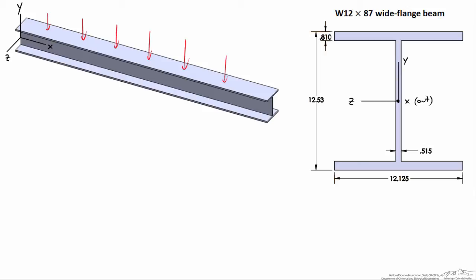And consequently, we want to calculate the area moment of inertia about the z-axis, and that's equal to the integral of y squared dA, where y is the vertical distance from the centroid. Note that how you typically see this reported in reference manuals, you'll typically see this being the x-axis and this being the vertical axis. I'm keeping it the z-axis to be consistent with the isometric view. But just keep that in mind. What I'm calling IZ, you'll typically look up, and it's called IX.